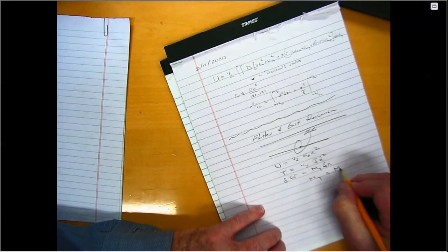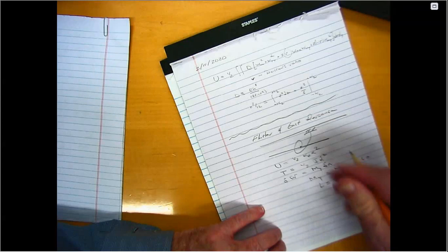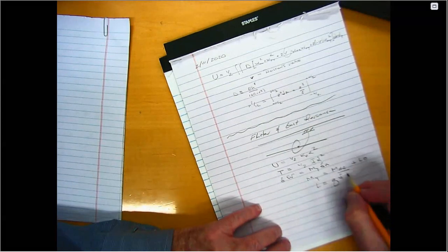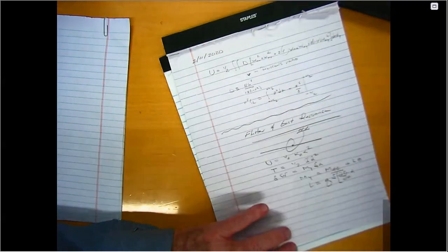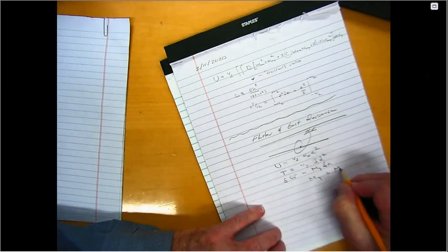And the lift, in this case, is just q times the area of this simple wing times dCl d alpha times alpha. But now, because we're doing dynamics, we want to recognize that this lift might not only depend on alpha, but it might depend on the time derivative of alpha, on alpha dot.